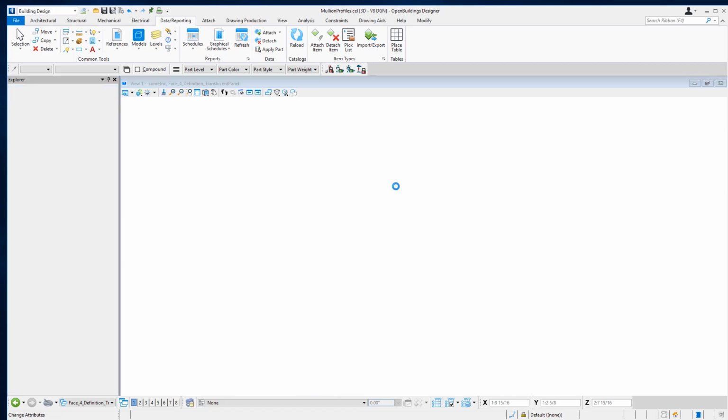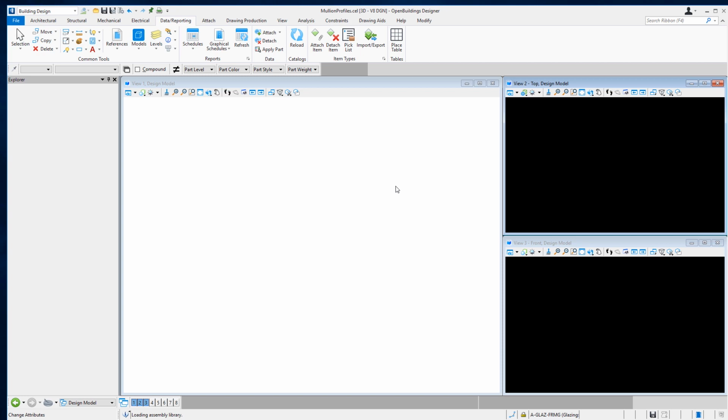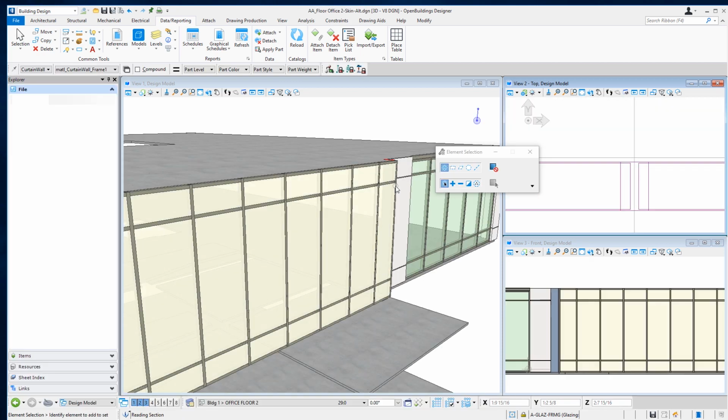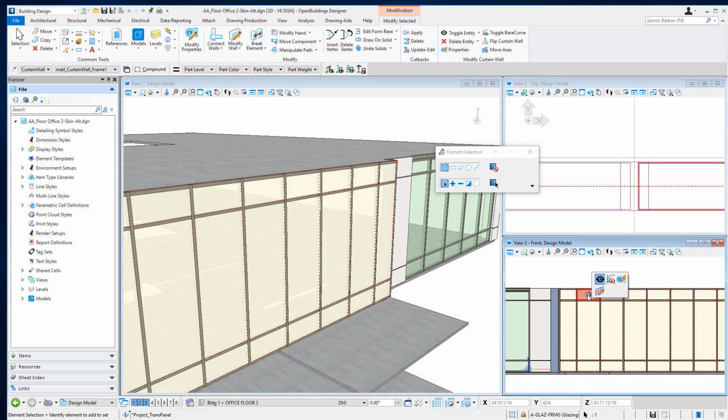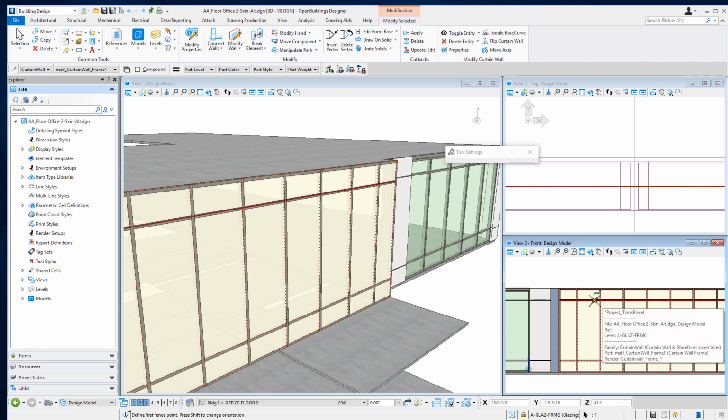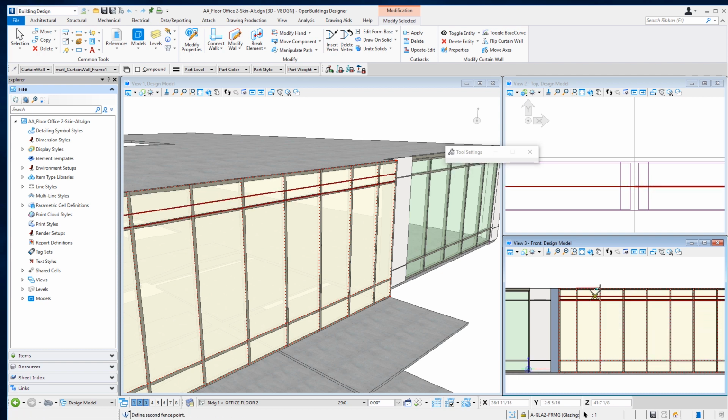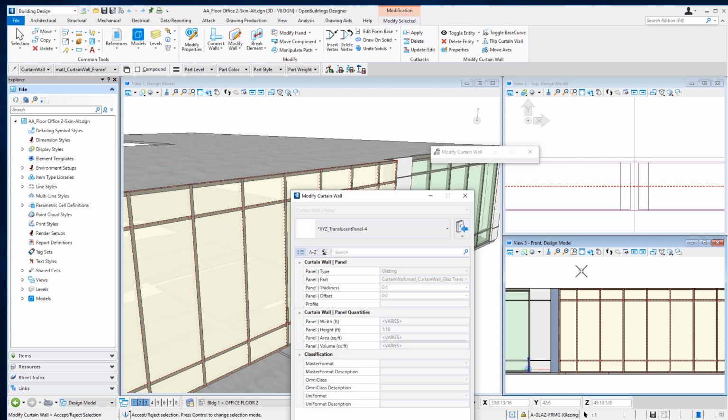And now we'll go ahead and go back to our 3D model, and I'm simply going to replace these panels in my system with the new parametric panel I just created so that we get that grid. So I'll start with the upper ones here. I'm going to select one of those panels. Now I can multi-select the entire line and simply define the range by selecting the bottom mullion and then the top mullion that then defines all the panels.